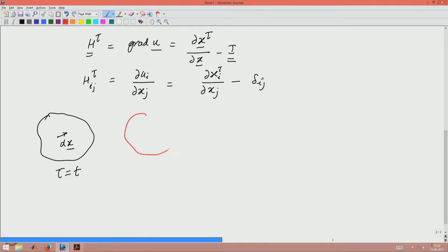And at any time in the future, the same two material points are of course connected through another material fiber, which we will call tau, where tau is greater than time t. So, how the relative location as well as orientation of these two material fibers changes is what is indicated if we evaluate a quantity like this.